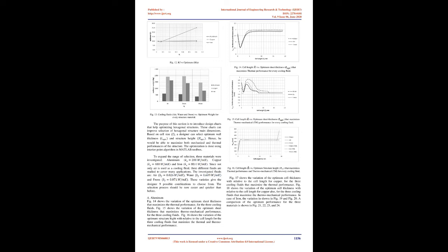Such difference is due to cellular materials are load-bearing so that shear modulus is of interest. Porosity also is an important aspect when utilizing sandwich structures as compact heat sinks. To find the optimal cell topology that maximizes both thermal and mechanical performance, equation 13 was used.